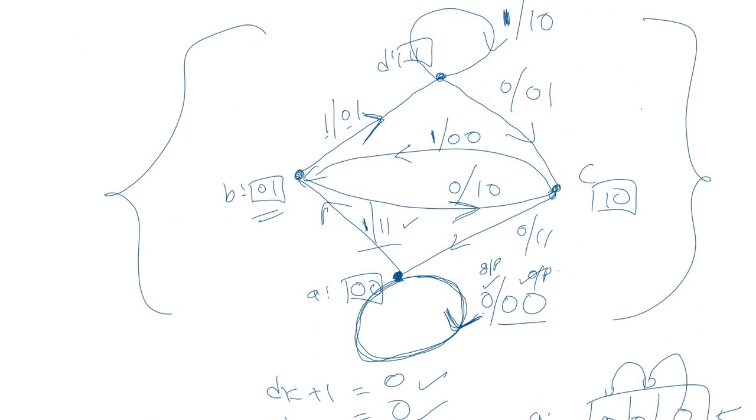I hope you are able to understand how to make this state transition diagram. We can carefully observe from this state transition diagram that the encoder can go to only 2 states directly by inputting a single data, whether the input is 0 or 1. This encoder can only transition to 2 different states. For example, if we are at state A, it can either transit to state B or it can transit to the same state A by inputting any data 0 or 1.